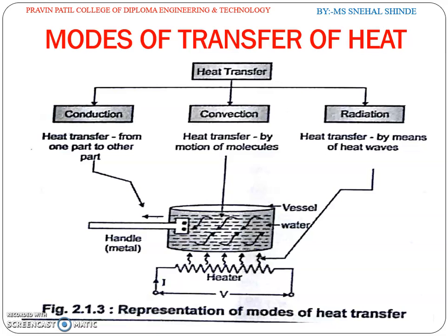For a vertical heating surface in air, the heat dissipated due to convection is given by Hc equal to 3.875 (T1 minus T2) raised to 1.25 watts per meter square, where 3.875 is a constant value that depends on the heating surface arrangement, that is, shape and size.